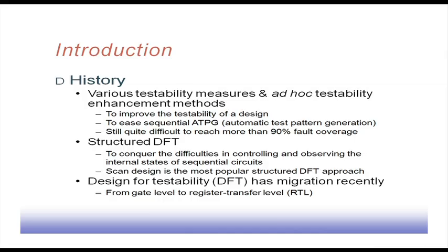So, that makes it more difficult. Putting some value to the internal flip flops becomes difficult. You want to observe and control the internal states, so that becomes difficult. So, what came up is the scan design. Scan design is the most popular structured DFT approach, because that will put all the flip flops onto a shift register, so that we can shift in the test patterns and shift out the responses from them.